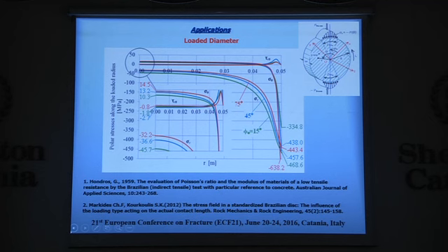And of course from the findings we have at the center of the disk and from this plot we see that the failure mechanism perhaps is more complicated in the transtropic disk, and certainly is completely different from the isotropic one. We can't draw safe results unless we first apply some failure criteria to identify the critical points, and of course supplement our work with some experimental or perhaps numerical findings.